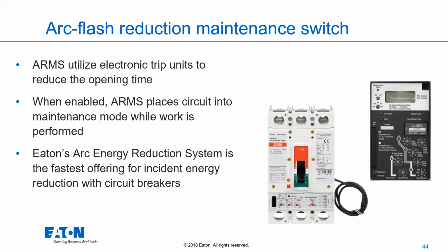A lot of these fancy trip unit breakers have that purposeful six cycle delay, like what we saw in that other one. And that's for coordination reasons, right? These are breakers that are higher up in your system, and you purposely want to wait to see if downstream devices will open instead. You don't want to cause a blackout for your entire facility because one trip unit wasn't set correctly.